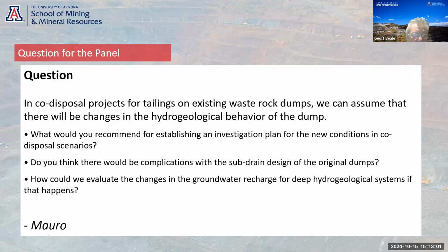And so that potentially, firstly, may affect the stability of the dump. It may, as you say, give more water at the toe that you have to deal with, and it may give more downward infiltration. So I'm assuming the question is that you're looking at putting a low solids tailings onto a dump without a liner. There's not that much precedent for that, I don't think.